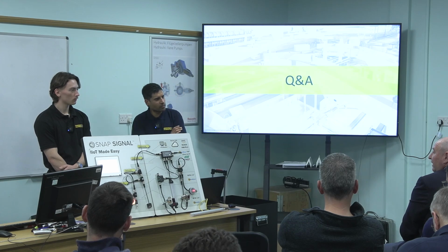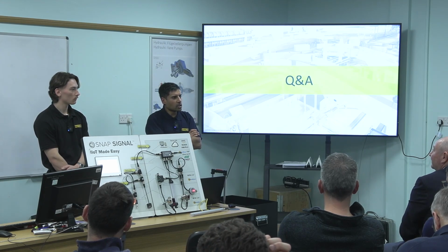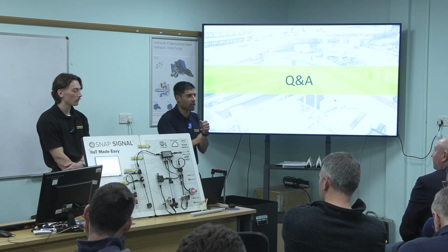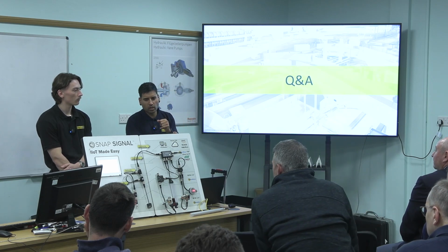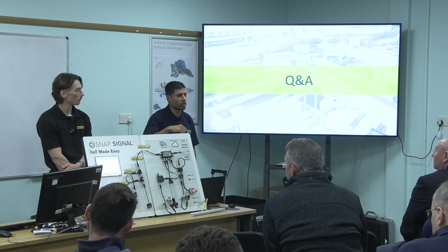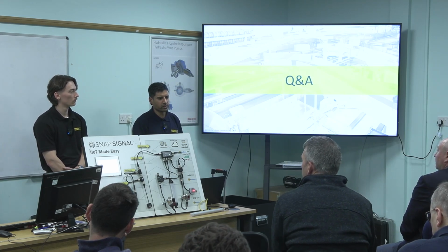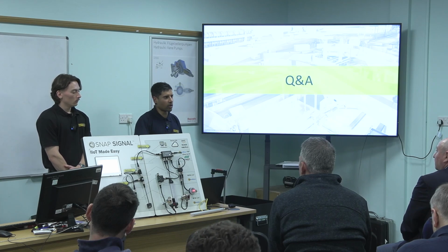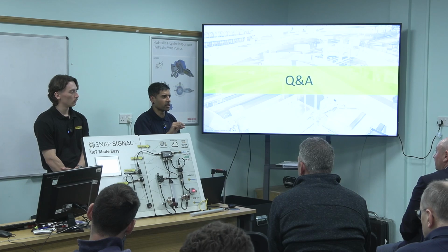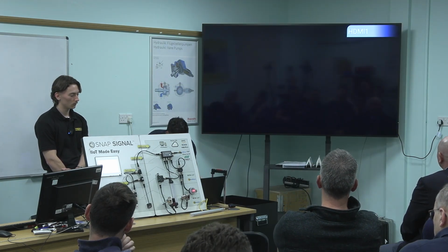How user-friendly then is the software when you are doing conversions? Is that something you have to do in-house, or is it something the customer can do? Yeah, customers can do it quite easily. Everything's got slave ID as one, so you can program that. You don't even have to use our software. You could use Modbus Poll, and you then set the IDs for each of your devices, because being Modbus, everything needs to have an ID. But then the register map is, if I show you, just simple.